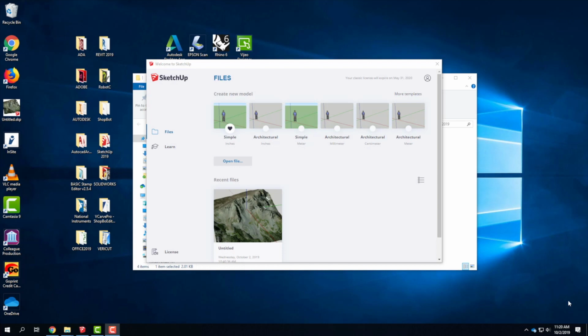The first thing that we need is some kind of a source of the terrain information to begin with. You could have terrain information coming from a surveyor or from some model that pre-exists that was given to you as part of your design process. For our purposes, we're going to pick a piece of terrain and use the SketchUp Geolocation feature to get that piece of terrain. It's not the most accurate piece of terrain in the world, but it is a place to start, and it's something that everybody can pick from. So that tends to be a good thing.